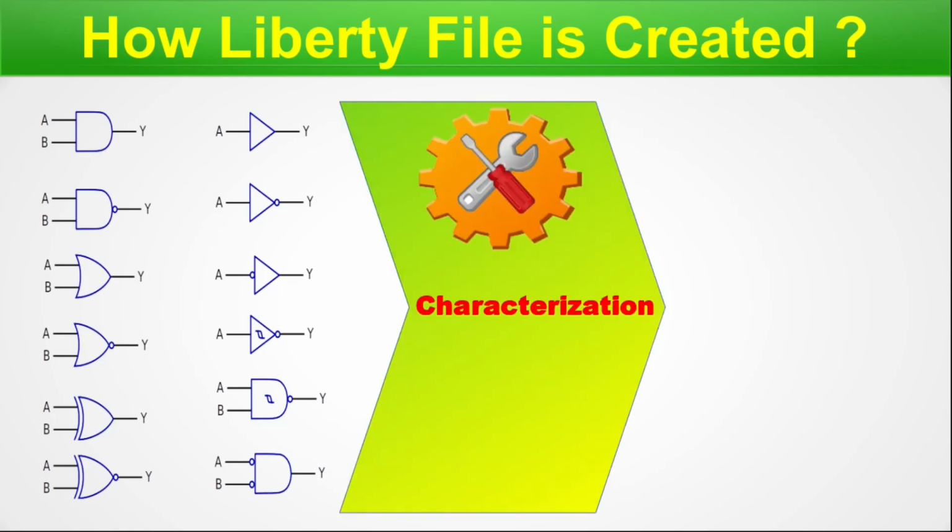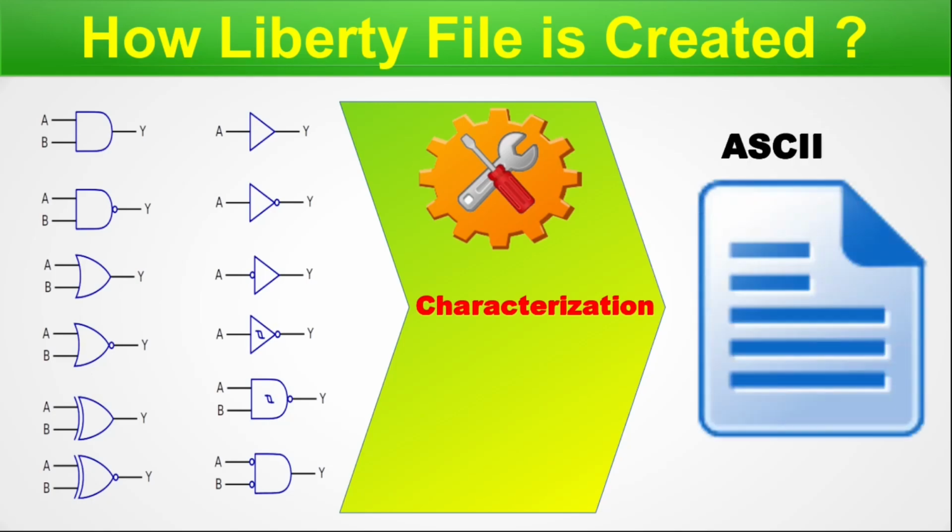In the standard cell characterization, the engine picks up the necessary views for the characterization and runs the dynamic timing analysis, which is already explained in episode 1. In case you have not seen episode 1, I request you to use the chapter facility in the respective video description to quickly navigate and see the relevant section. Now, the characterization process gives birth to the text output file called the .lib file. Now, let us get a bit more closely familiar with this file.